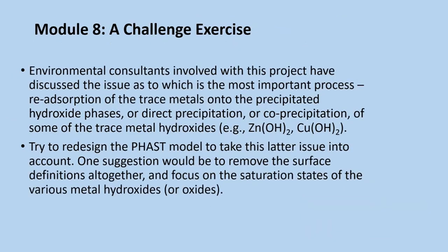So, with all of this in mind, I have a challenge exercise I would like you to look at. Environmental consultants involved with this project have discussed the issue as to which is the most important process: readsorption of the trace metals onto the precipitated hydroxide phases, or direct precipitation or co-precipitation of some of the trace metal hydroxides, such as zinc hydroxide, copper hydroxide, and so forth, as a result of the pH increase from the reagent augmentation.